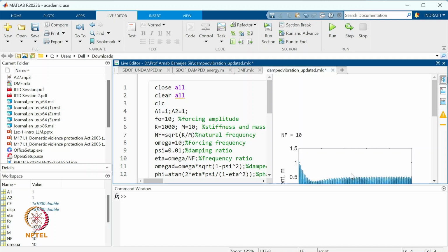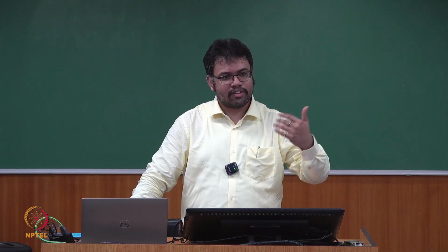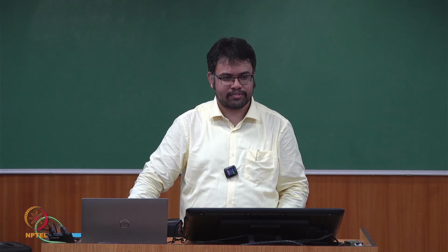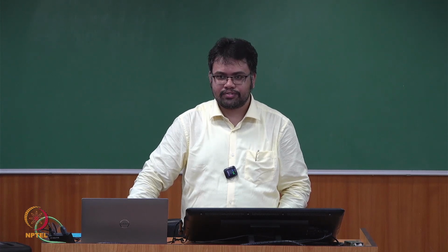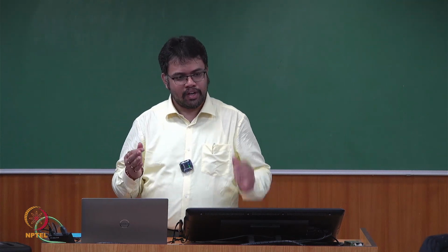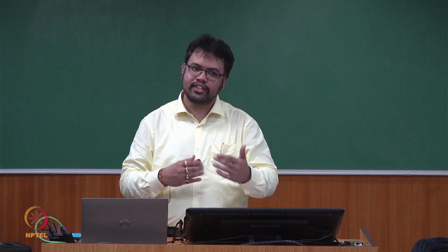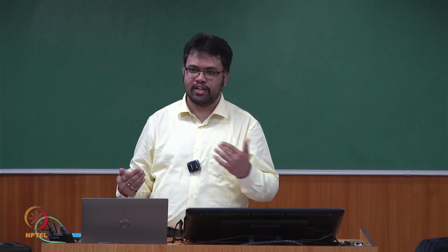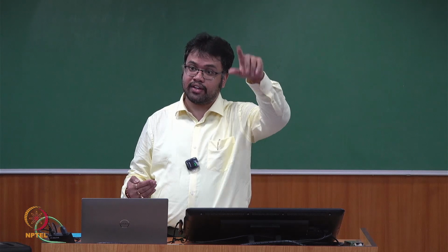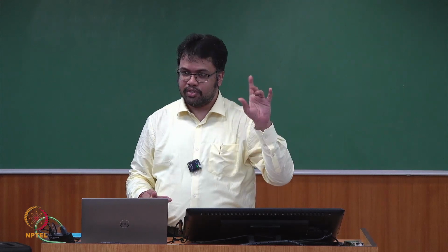So we cannot say exactly how long it will take; it depends on where we started. It depends on two things: the initial condition and how much the damping is. If you change the damping, it will take more or less time, because ultimately the decaying factor is e to the power of minus zeta omega t. That is also a very crucial point.